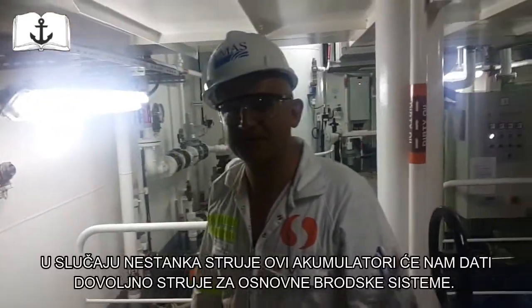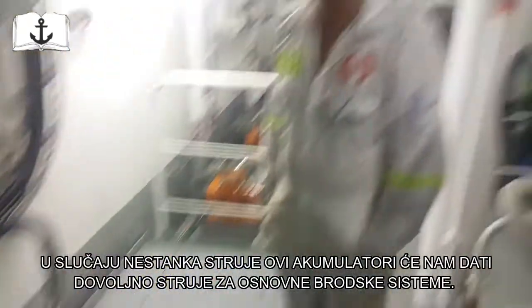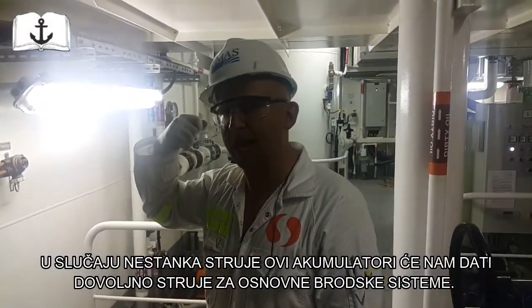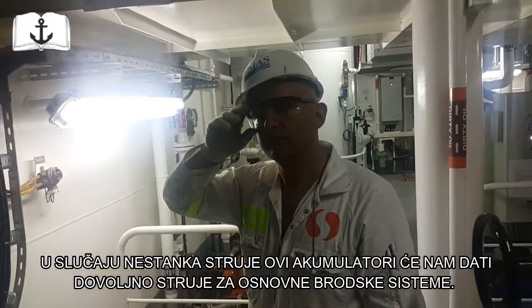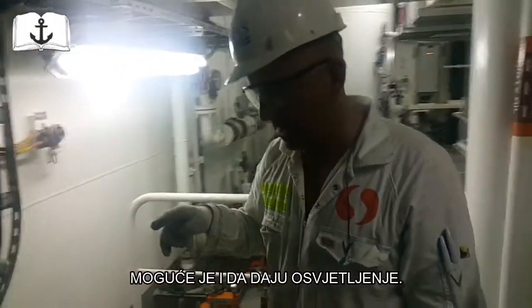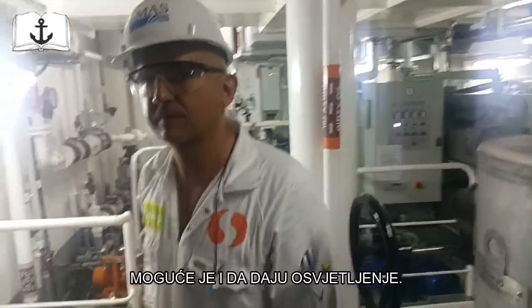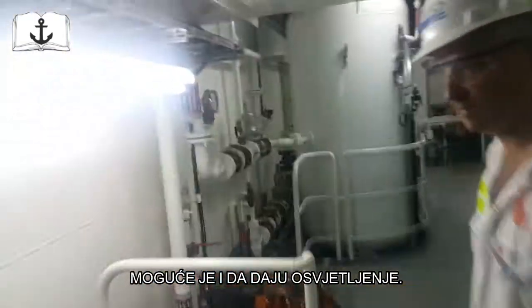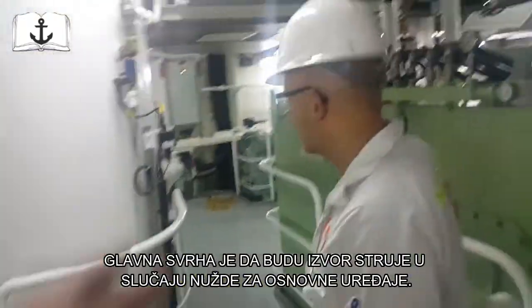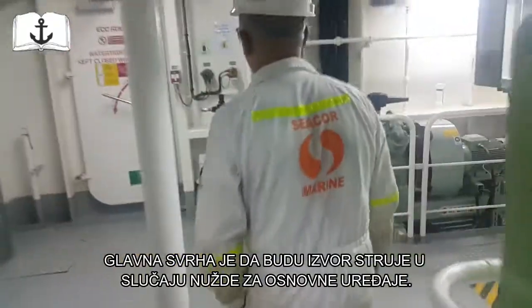So in case of blackout, what will these batteries do? They will give us the control voltage to the bus bar, where all the breakers are, which we showed in the beginning. The batteries can supply some of the lighting, it's possible also, but the primary purpose is to supply power to the bus bar. Control power, it's not the main power. Control power, good.